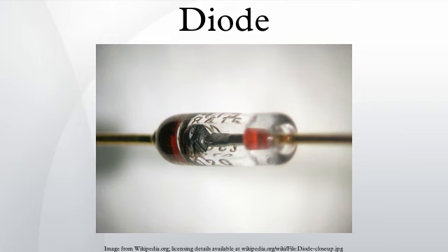Light-emitting diodes. In a diode formed from a direct band-gap semiconductor, such as gallium arsenide, carriers that cross the junction emit photons when they recombine with the majority carrier on the other side. Depending on the material, wavelengths from the infrared to the near-ultraviolet may be produced. The forward potential of these diodes depends on the wavelength of the emitted photons. 2.1 eV corresponds to red, 4.0 eV to violet.